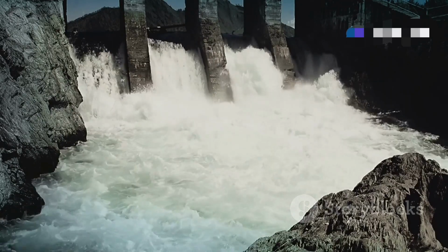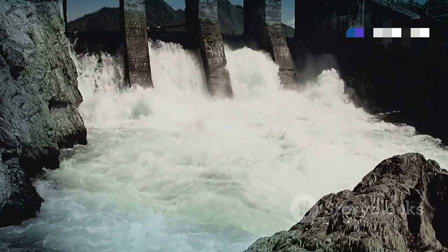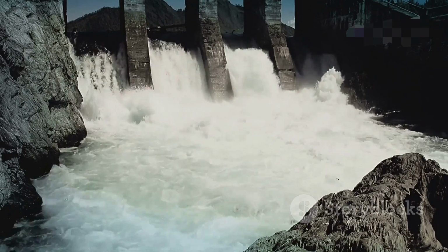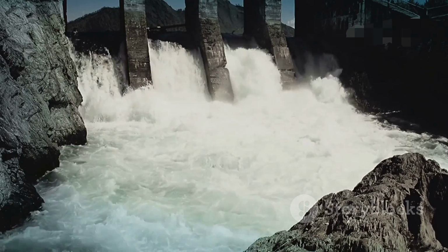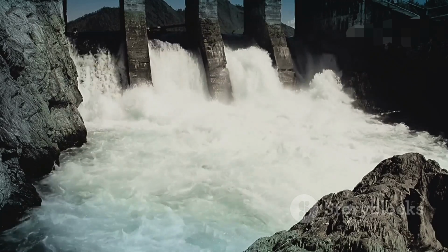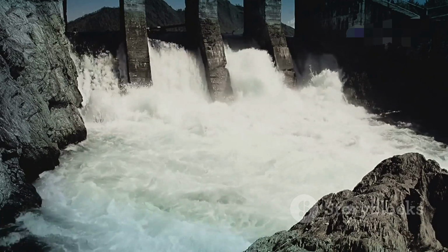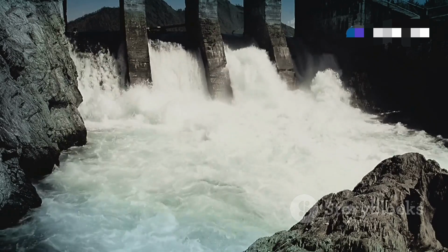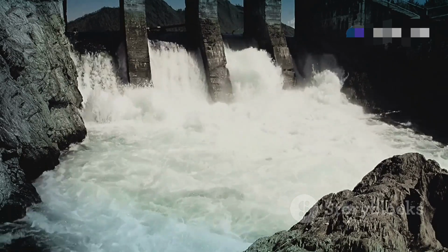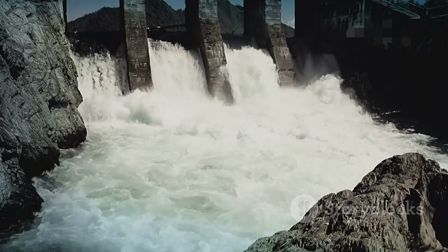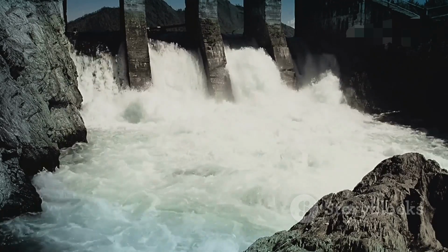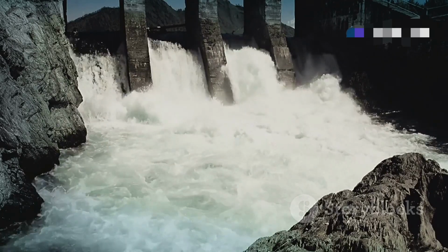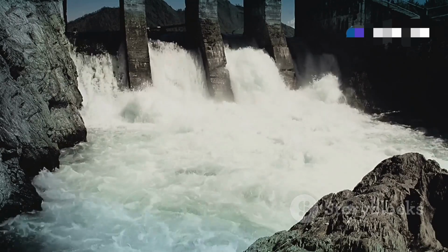For most earthen dams, the breach is often assumed to erode down to the original streambed or a non-erodible layer within the dam's foundation. This means the breach depth is effectively the height of the water behind the dam, or the height of the erodible material. In some cases, there might be a hard rock foundation that limits how deep the breach can become. For concrete dams, the breach depth might be determined by the height of the failed monolith or section. Careful site investigation can help identify potential limits to vertical erosion.